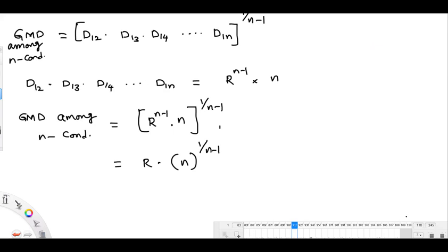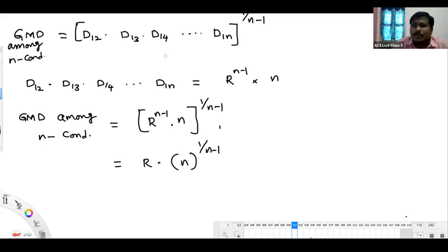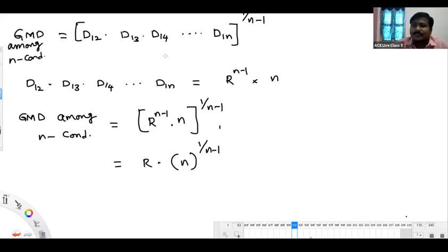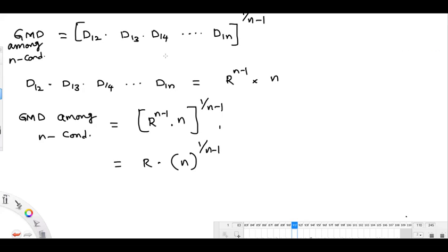What I'm asking is whether the internal flux is due to eddy current formation. No, that is simply due to current flow inside the conductor. That's it. Eddy currents and all we are neglecting. And the external flux is outside the conductor, that links to the other conductor. Okay, sir. Thank you.